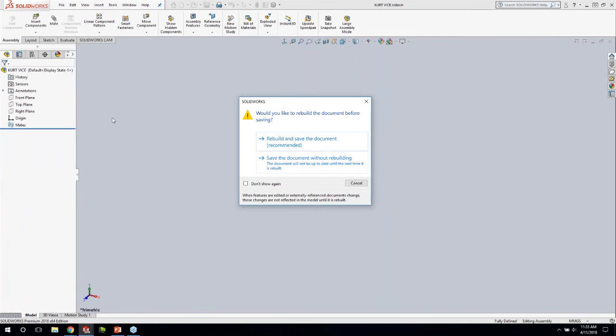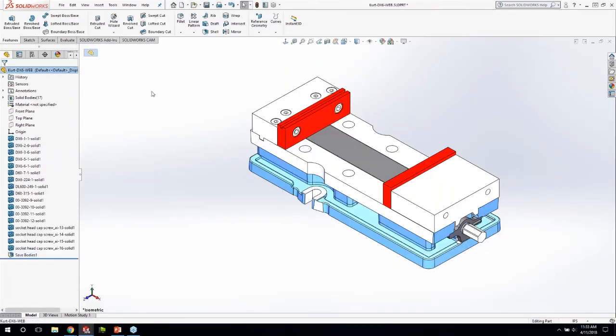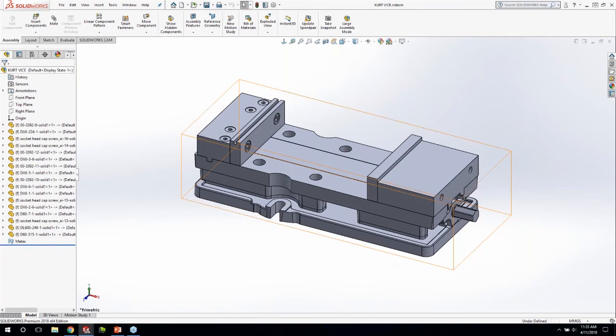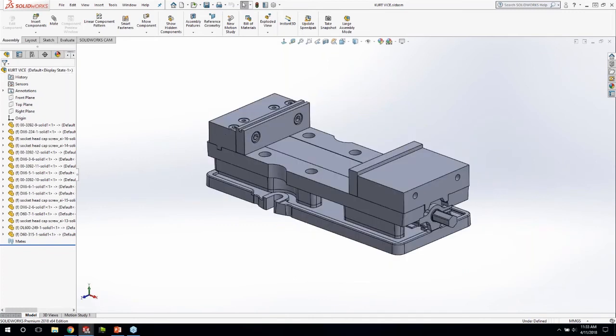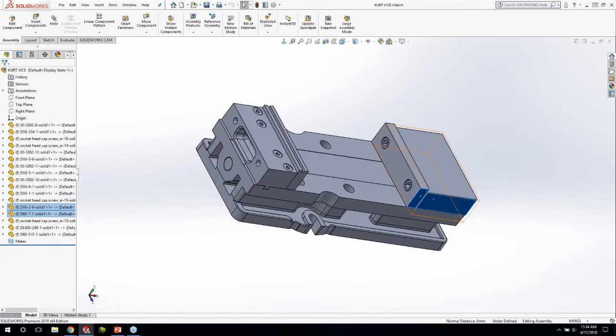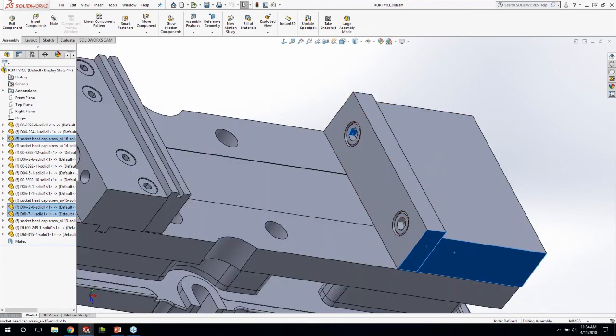And you can see here that we have the original part. So we'll switch to this here. So this is a Curt Wiss assembly. Of course, everything is just going to be kind of imported, fixed in place in 3D space. So if you wanted this to be functional, we can go ahead and float the moving components. So if you wanted to find where these are in the tree, you can go ahead and do that, or just control select them like this, right?